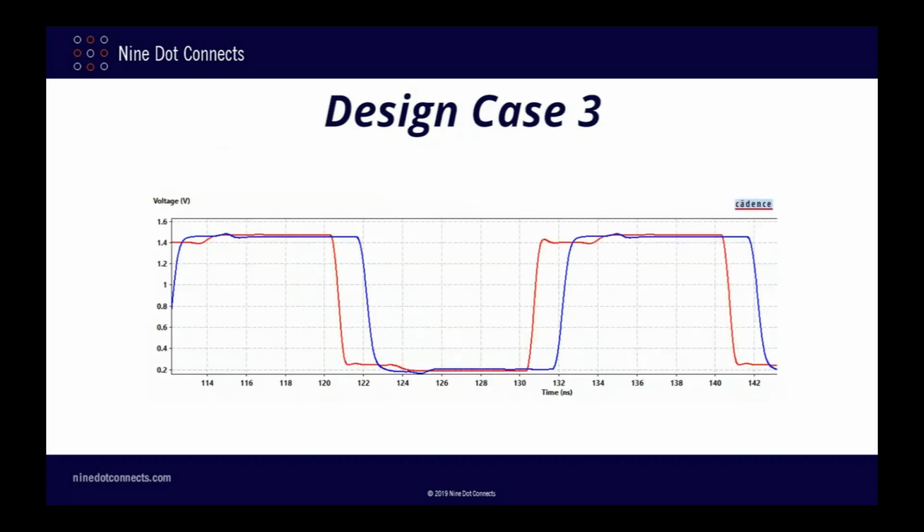After running the time domain simulation, we find almost exactly the same waveforms as before. The signals are a little bit cleaner as a result of the better behavior of the strip line S parameter graph, but otherwise they look almost exactly the same. In fact, they were so similar that I was worried that I had done something wrong in my simulations. After all, my premise was that the signal timing should be different between the two routing styles, and I didn't really see that here. However, it turns out that this was just a matter of scale.